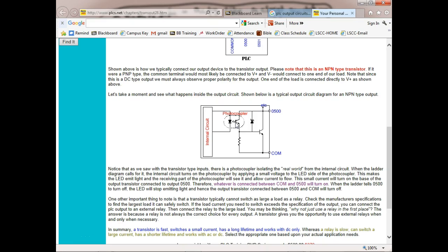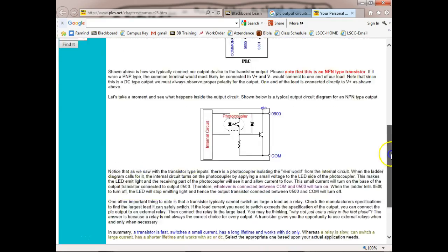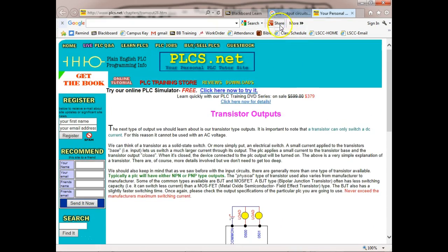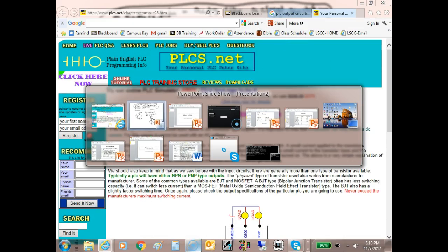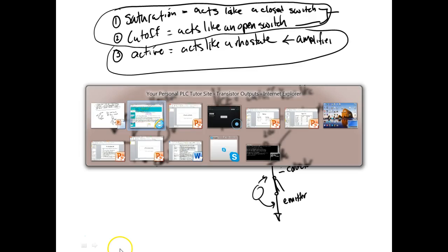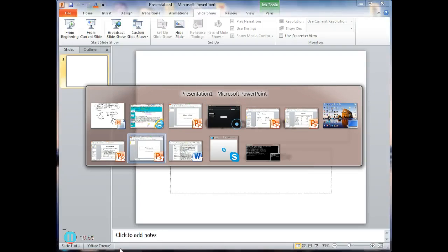Now, well, this is actually a DC output. This would be a sinking output. So all they use is saturated switches. That's all they use. And that would be DC output. So we want those things to be either switched between saturation and cutoff. If I come up here and look at an amplifier, though, we're not going to see any switches inside that thing.